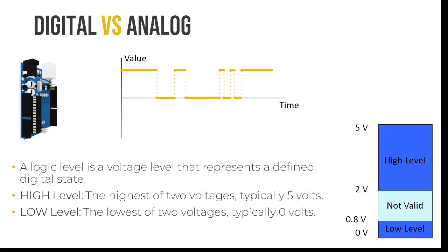Okay? This is useful because maybe to our Arduino Uno we can connect a sensor of 3.3 volts, and you will detect the 3.3 as what? As 1, right? Because 3.3 volts is right here. So for the Arduino, it's the same if you send 5 volts or 3.3 volts. But you have to be careful because if that sensor needs you to send some voltage to it, you cannot send 5 volts to the sensor. It will burn because it's 3.3 volts. So you can read without problem, right? It's a little problem, right?